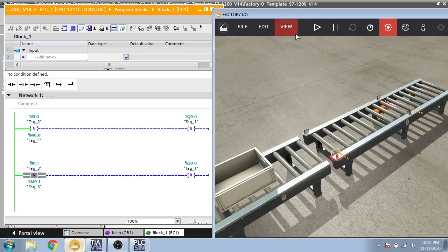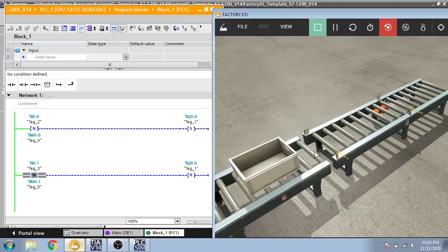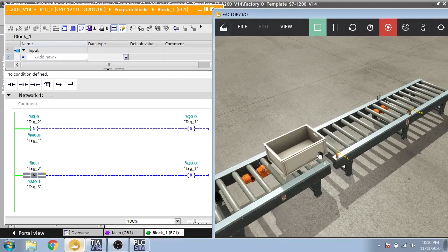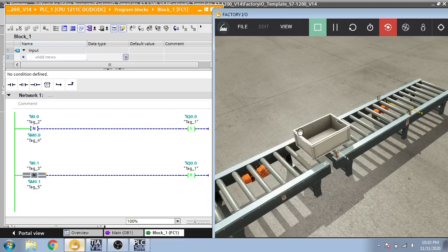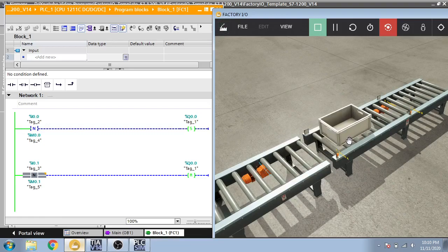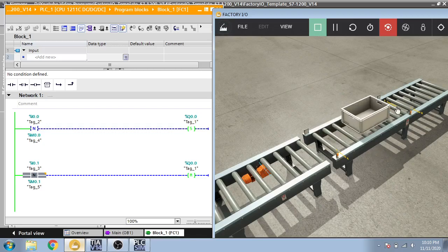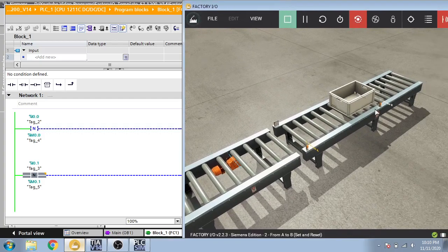So you can see in the first, when it touches the sensor, just in front of the sensor, the second conveyor is now in running mode. When it touches the sensor, the conveyor resets. That is because it is an NC sensor. So that's the negative edge we used for the NC sensor, for when it touches the sensor. The sensor works and our logic will continue.